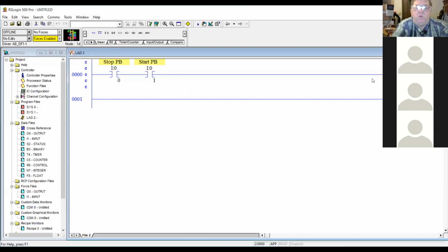So here, you would put the letter O, and you've got to be careful to put a letter in there, not the number 0. It has to be a letter O, and it's going to be nice and round. Colon, and then it's going to be slot 0 because it's built into the PLC. This is embedded outputs, not an individual add-on slot. And this / and it's actually output 0 in the output section.